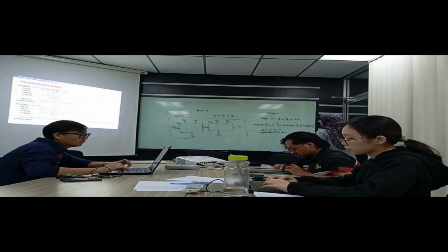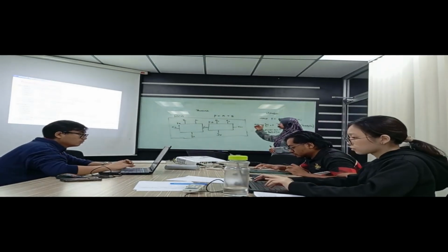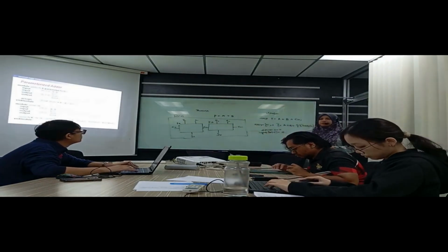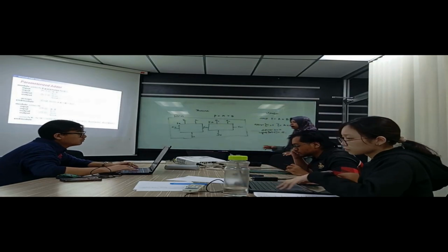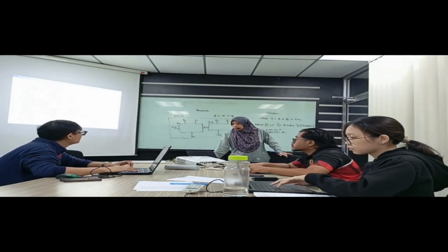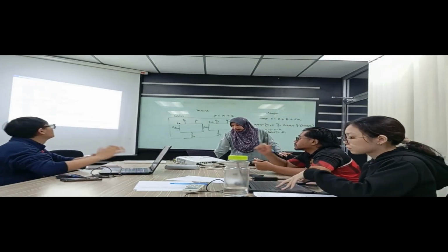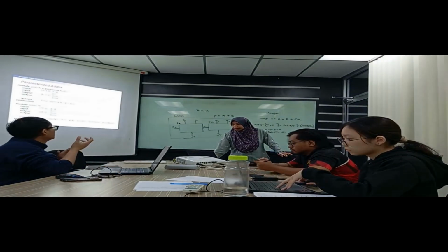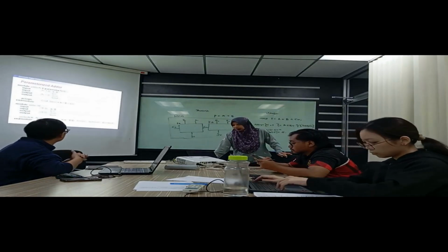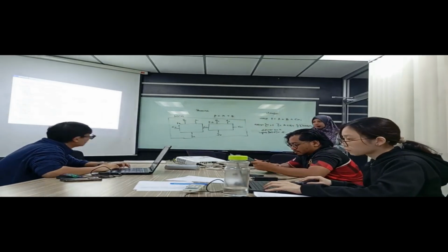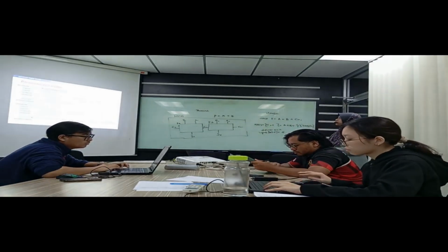Remember that the original parameter value can be bigger or smaller than what you want to design. For example, this one can be 32, but you want to design 16, no issue. Or this one maybe can be only 4-bit, and you want to design 16, no issue. That is the flexibility of parameterization.